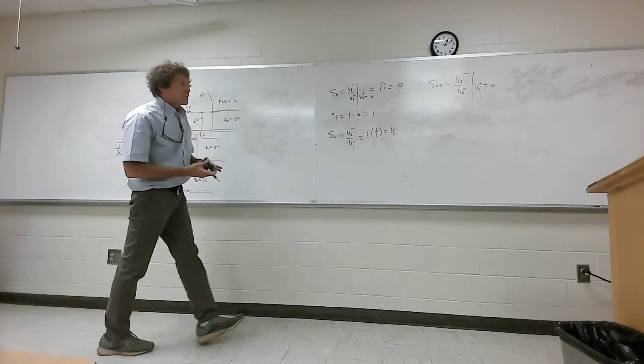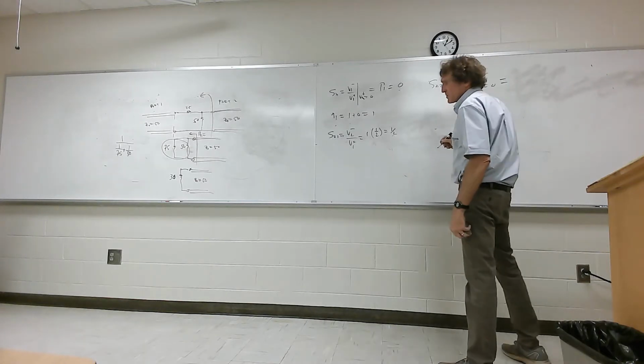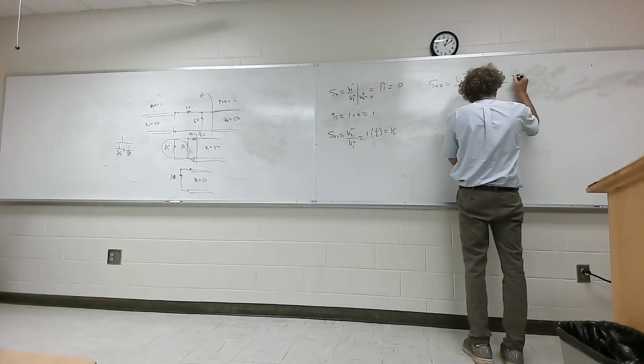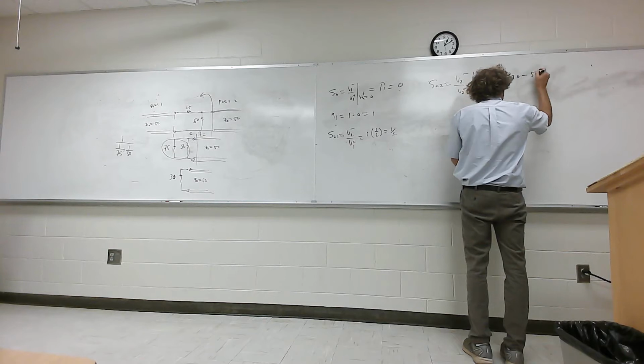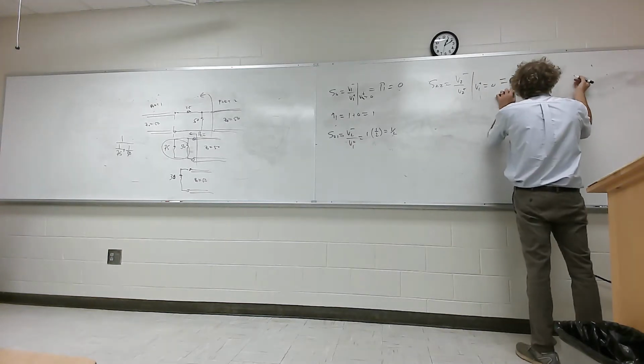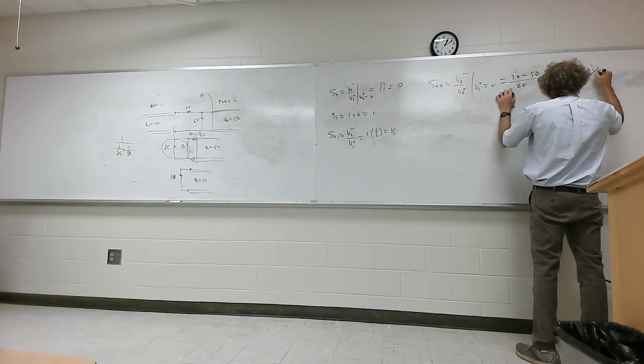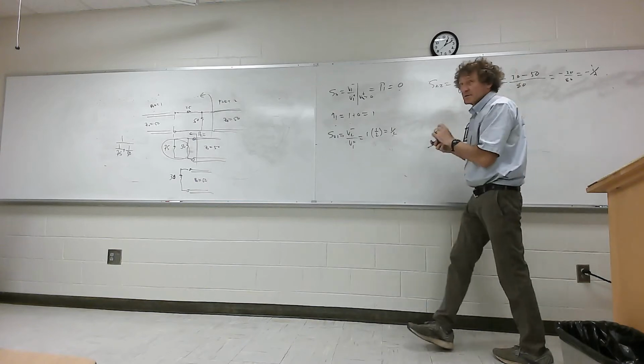So that means S22 is going to be the impedance you're going into, which is 30, minus the impedance I came from, 50, over the sum of those, which is 80. So that's minus 20 over 80, or minus 1/4, is the reflection coefficient. Do y'all agree with that, class?